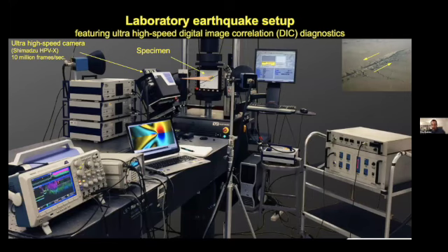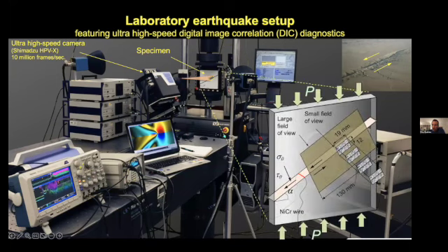So let me start by showing you our laboratory setup. Here we have the specimen at the center, unloaded in the vertical direction. Here you can see the specimen with the vertical loading, and basically the faults are represented by an inclined interface made by two quadrilateral plates put into contact. The vertical loading results in a resolved level of normal and shear stress on the interface. Ruptures are nucleated by the small burst of a nickel-chrome wire placed across the interface.